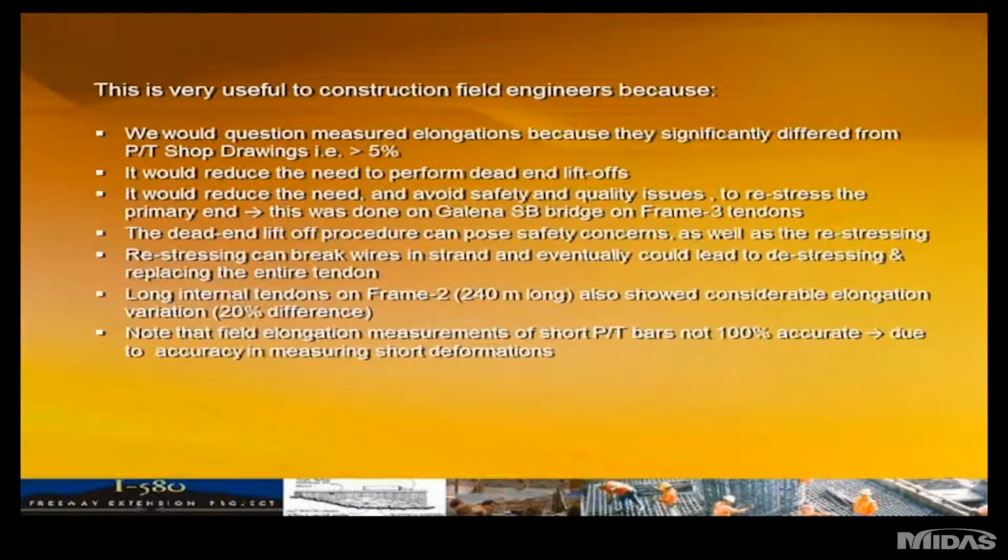Why is that useful? Well, it's useful because, as I mentioned, the elongation control, you want to keep it within plus or minus 5%. If it doesn't, then obviously the design engineer has to get involved in order to confirm that he's going to accept the stressing results.